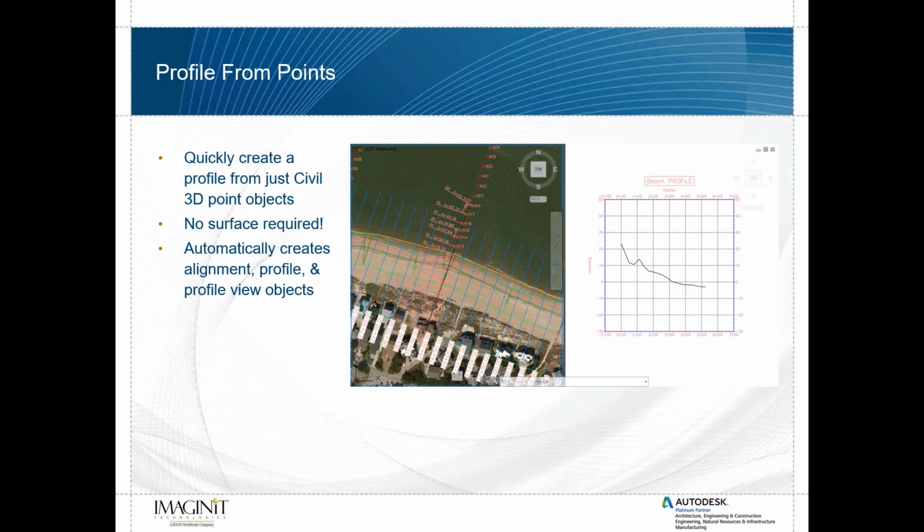But we have had occasions, I'm sure, that you've gotten a survey, and you either get a simple cross section from a survey or the path for a proposed location, typically of some sort of utility, and all you get is a handful of shots, not enough to create a terrain. But throughout those series of shots, you have the path that you would like to create a section from. And we're not going to create a cross section. It is on the fly, based upon your selections, going to create an alignment profile for you. Really, really hot. I used to have a whole workflow for this, and we just combo it up into a really, really sleek tool here.